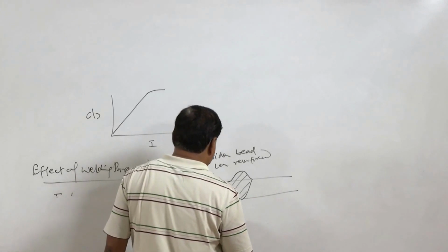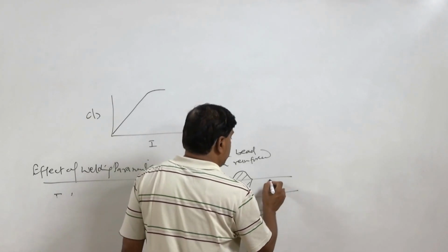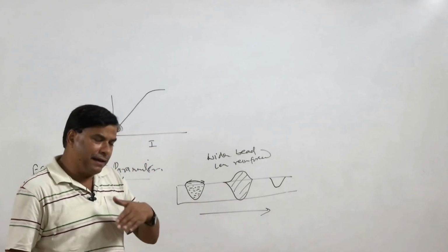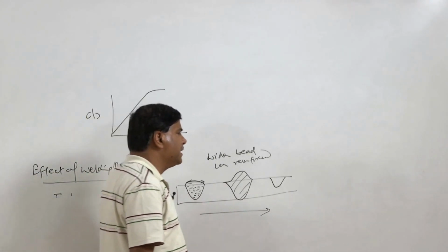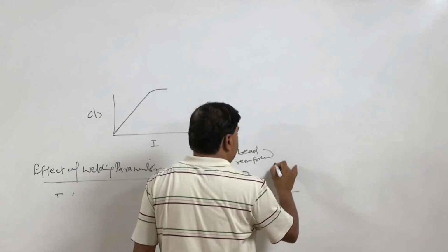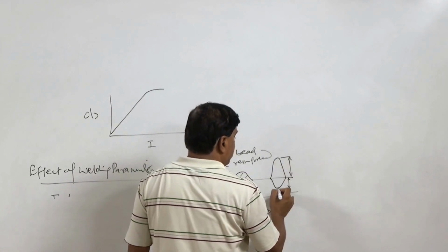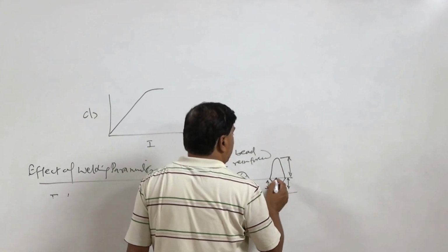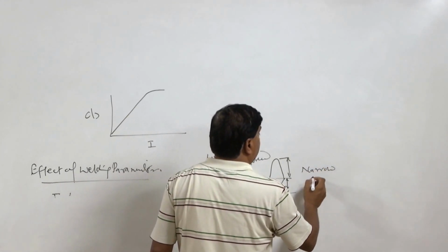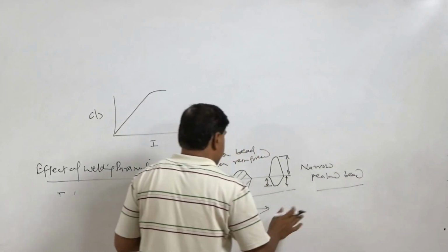But if the speed is too high, this is in increasing order of the speed, further increase in speed can decrease the heat delivery significantly. This can lead to reduced depth of penetration and a very peaked bead can be formed. So, high reinforcement, very limited penetration, and a narrow and peaked bead is produced when a very high welding speed is used.